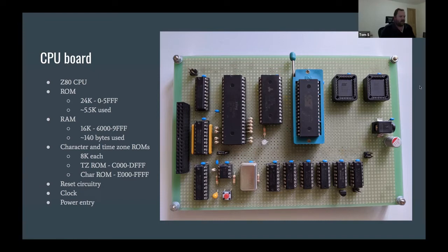So if I push the reset button, it'll generate a pulse, I think set at about 200 milliseconds or so. In a way, it debounces the reset button and provides just a single reset pulse to reset everything back to defaults.